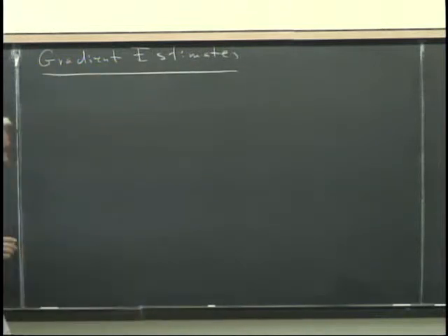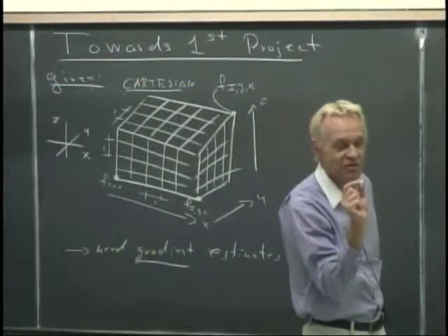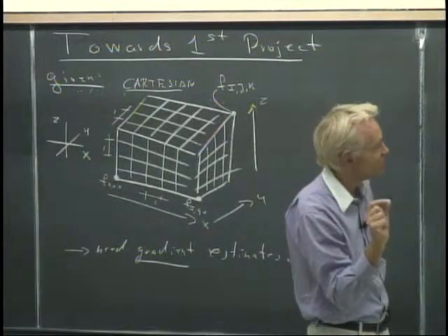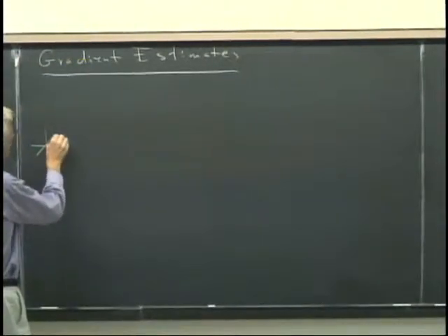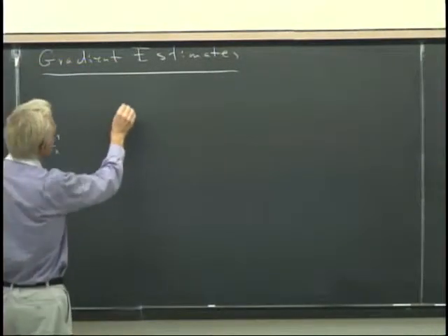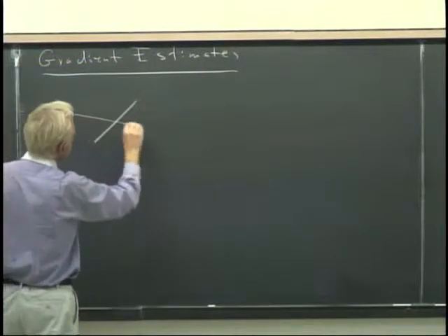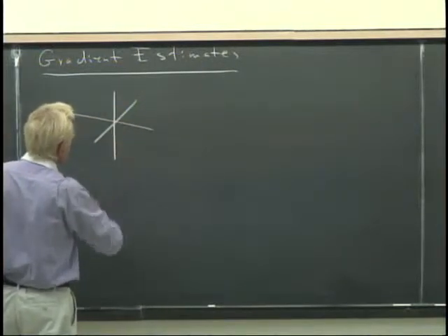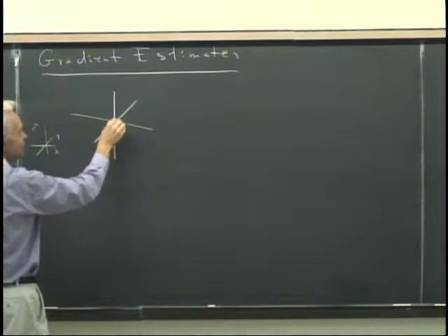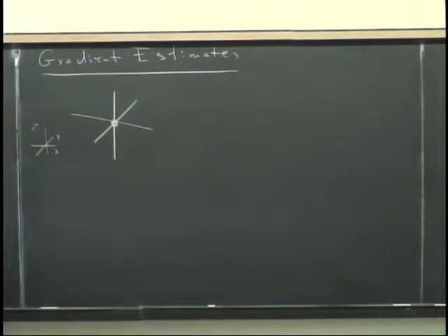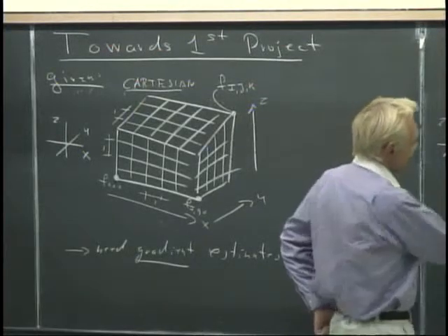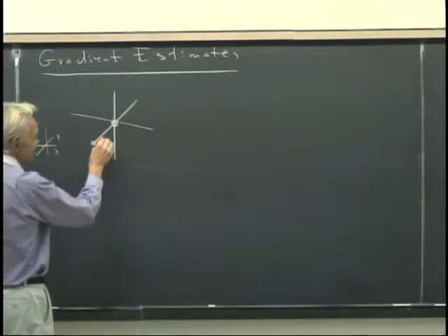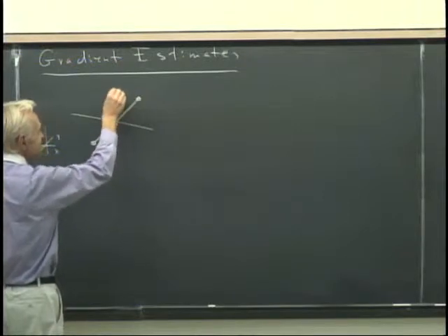Again, we only need to understand how to obtain the gradient at one of these locations, one of those points. If we know how to do it for one point, we know how to do it for all the other points. So in XYZ space, we have this configuration. We have a particular location, ijk in terms of index, but ijk is also the coordinate of that point because we are Cartesian. And then this guy has 6 neighbors in this Cartesian mesh.